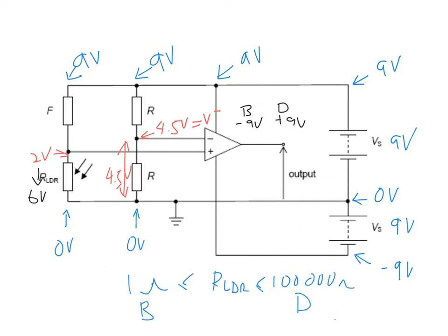So if you want to connect a relay to turn on the light, this is how you connect it. You put the relay here. Now what is a relay? A relay is actually a solenoid. For the solenoid, you must put a diode first. Then you put your solenoid here. Then you put your switch here. Okay, so this is your relay switch. Then you connect to an external light source, let's say a battery, and then you connect to a lamp. So that is your light source, a lamp and your outside battery.